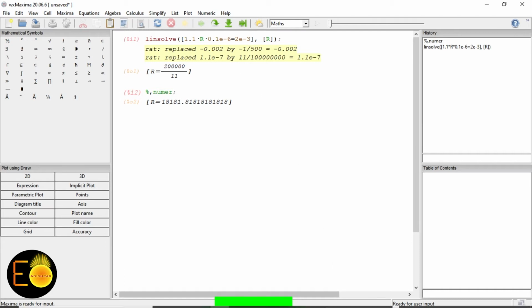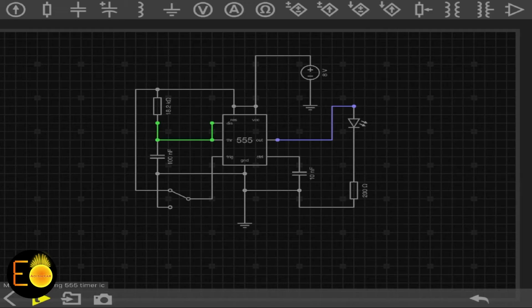So let's see using this animation. Now look at that. The value of the capacitor is set at 100 nanofarad, corresponding to 0.1 microfarad, and the value of the resistor is set, this one is the resistor and this was the capacitor, and this resistor is set as 18.2 kilo ohm. So I must expect that the waveform should be of 2 milliseconds, although here I am not showing you the pulse width or the duration for the quasi-stable state, that will be seen in the LTspice platform.